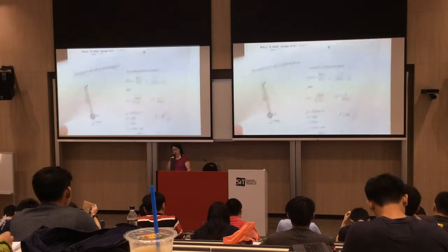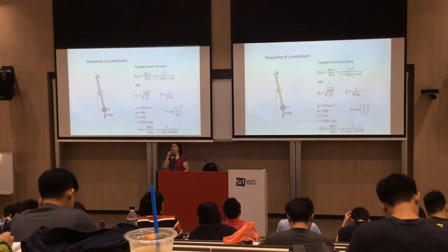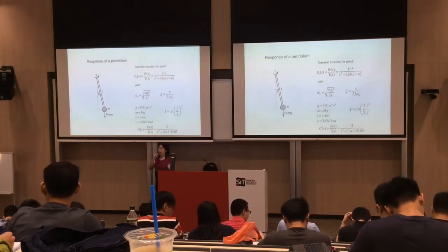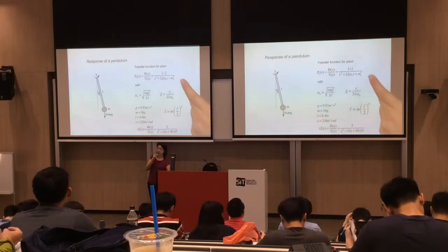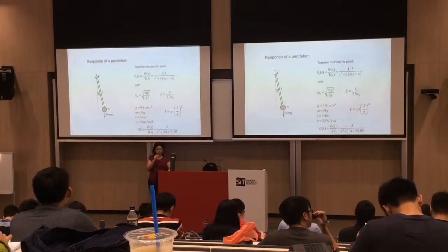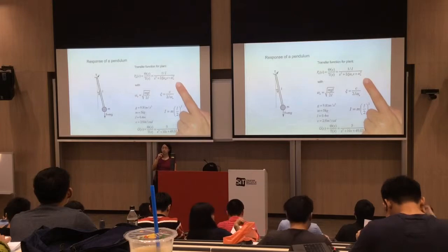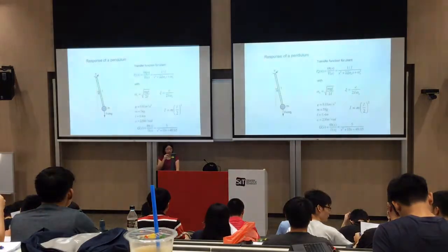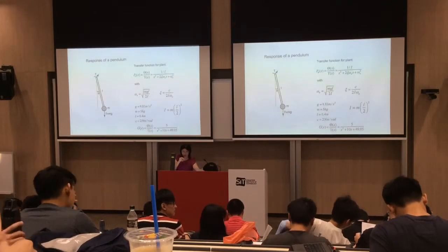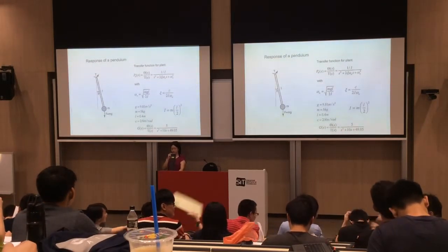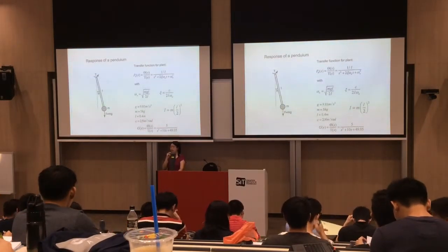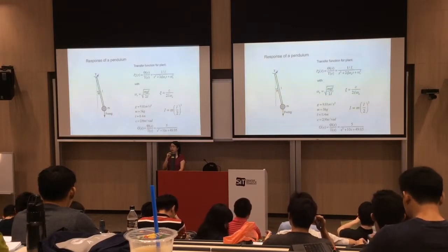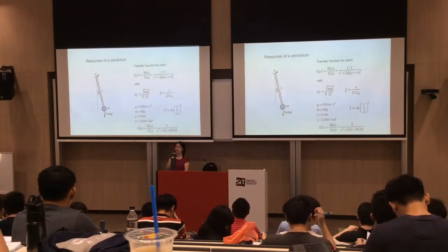Okay, and if you have a pendulum system, we covered this as well. Then we can derive this transfer function, and this is equivalent to a standard second order system. Given the parameters and the model, you put out the transfer function. What can you do with this transfer function? 5 over s squared plus 10s plus 49.5. How do you study it?